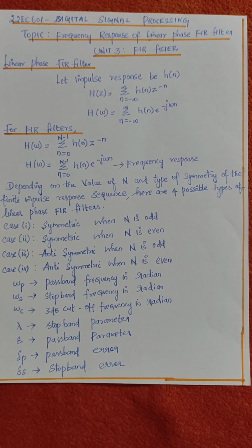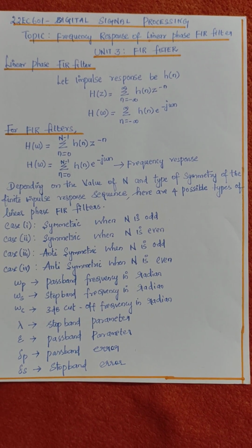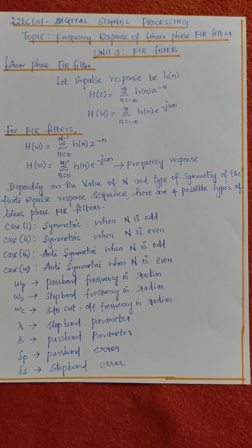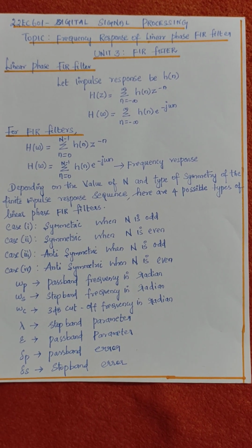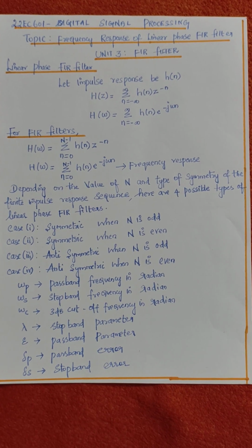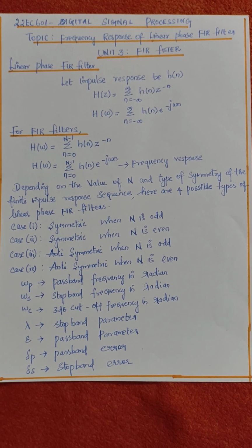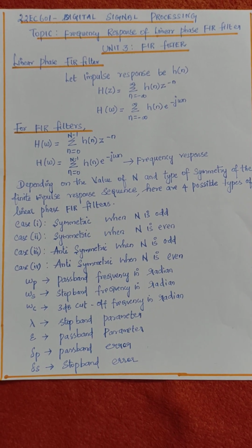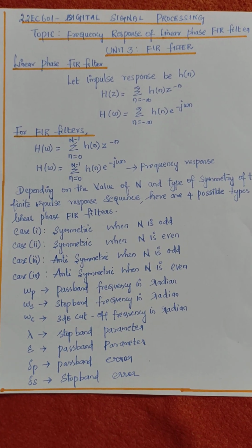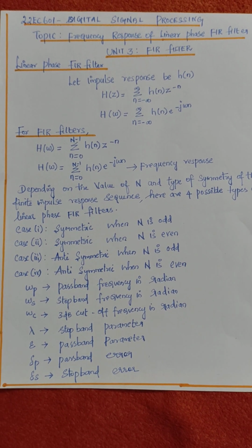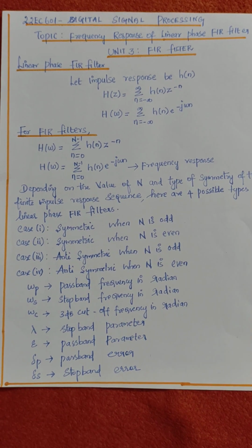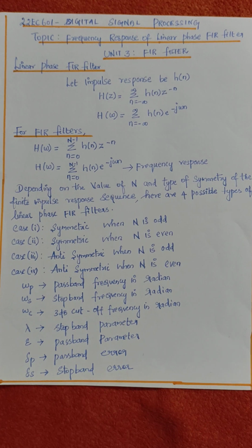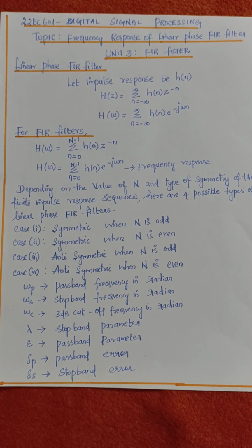The advantage of the FIR filter, a question will be raised. The answer will be, first point, it's linear in phase, or you can say it's a linear phase FIR filter. It's a keyword. Once you take the IIR filter, it's not linear in phase. Linear phase FIR filter, we're going to see today's topic in the third unit, FIR filter, the frequency response of linear phase FIR filter. First we need to understand what is called linear phase FIR filter.